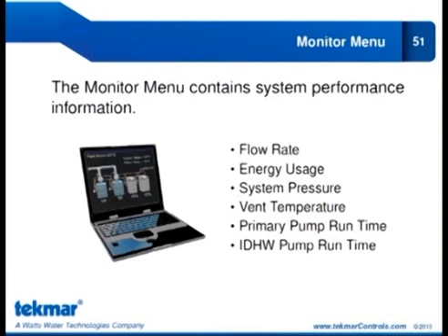And then we probably will OEM a vent sensor, which probably includes a transmitter. As you get into higher temperatures, you're going to require either a thermocouple or an RTD, which then can transmit a 4 to 20 milliamp signal, and that will be able to capture the higher temperature requirements which are experienced in a truly non-condensing boiler plant. So what the vent temperature does, well, if you look at just a condensing plant, for example, of course you understand that they all have their own internal vent sensor, which has its own logic, which basically protects the vent from extreme temperatures.